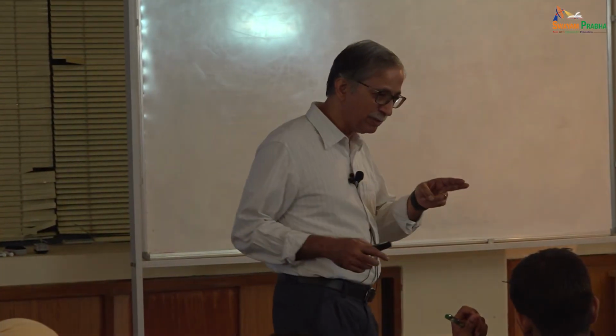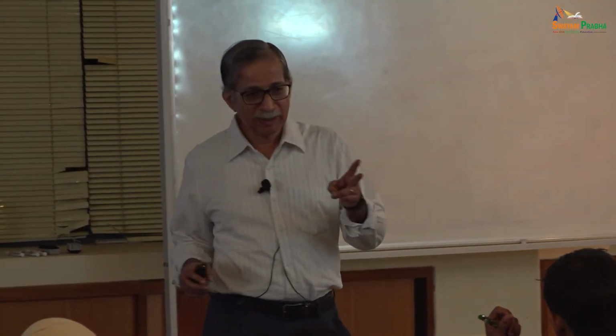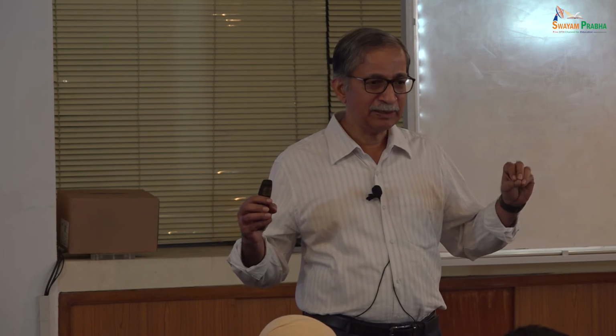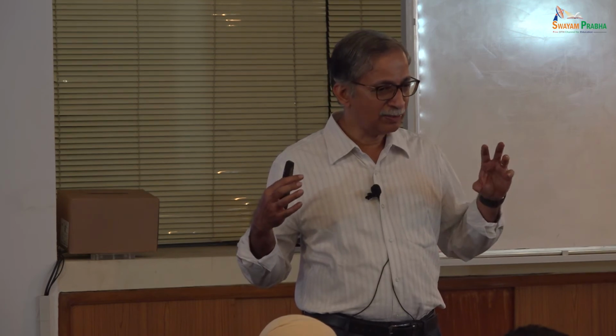There are two components to deflections: deflections caused by shear and deflections caused by moment. Deflections caused by shear are usually ignored because they are relatively small in well-proportioned beams compared to deflections caused by moment, by bending. In some cases they cannot be neglected. In which cases?